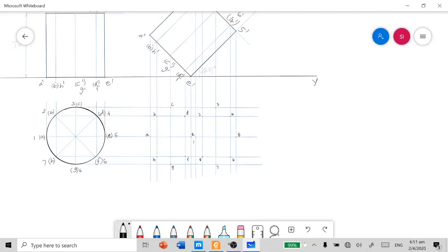The first rule is, you have to join all outermost points as visible curves or generators. Since it is a cylinder, there are no edges, so the base and face points can be joined as curves and the lateral generators will be joined like edges.